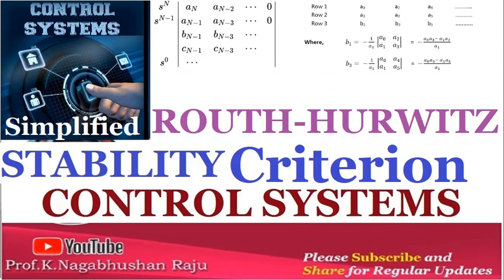With all the concepts of stability that we have learned so far, let's start understanding the Routh-Hurwitz criterion, or RH criterion for short. It is basically called the stability criterion for control systems. So far we know that for a system to be stable, its poles should lie on the left-hand side of the S-plane. And for any system, if the poles are on the right-hand side, the system is automatically considered unstable.